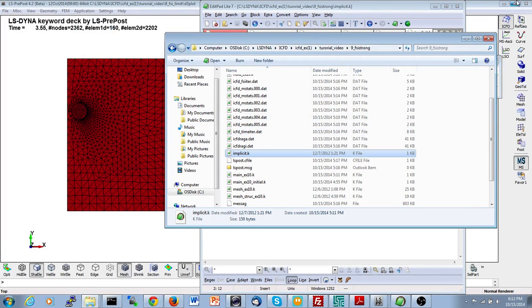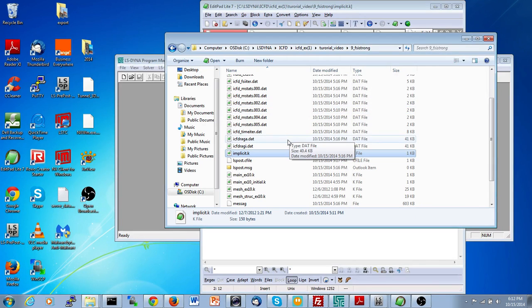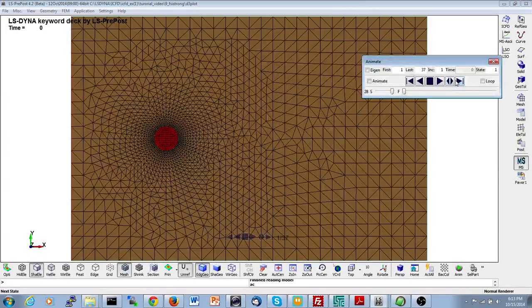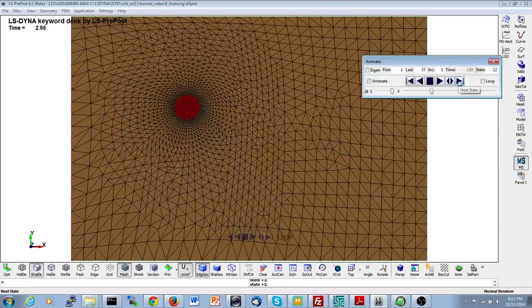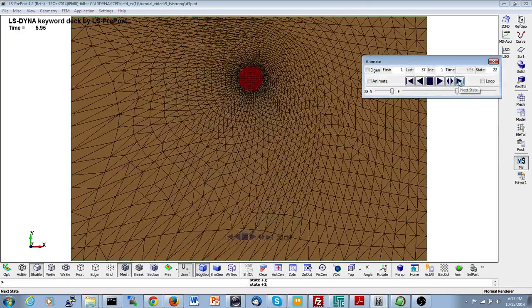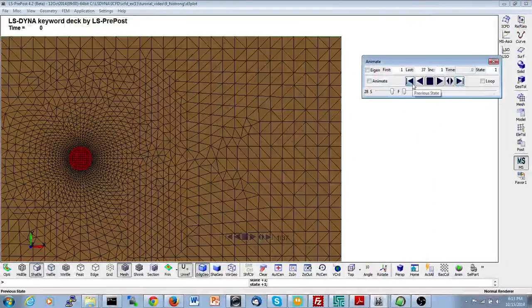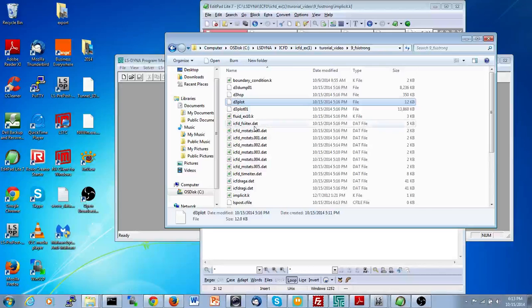But on the fluid part, there's no further modification of the input deck needed. Basically, if you use the explicit solid mechanics solver, you're automatically going to trigger loose coupling, and if you use the implicit solid mechanics solver, you will automatically trigger strong coupling, because there is no other way. There's no way to do otherwise. So now, after triggering strong coupling, if I start running the case, I will see that it behaves in a much better way, and it has a more consistent behavior.